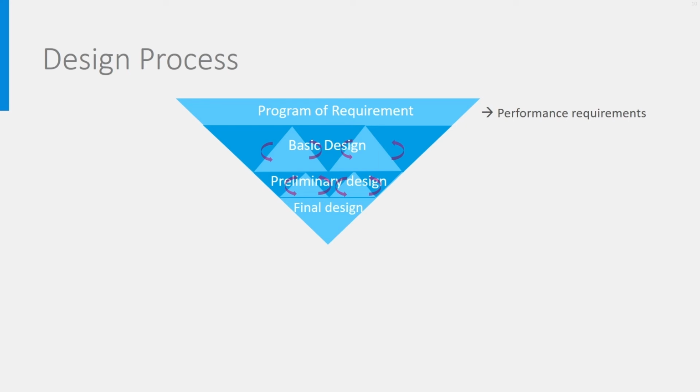After that, there may be a tendering or awarding phase, and the constructor will start with building the building and its systems. HVAC engineers may then play again a role in supervising the HVAC construction and taking care that all delivery procedures and needed checks are done. Think of checks about compliance of insulation, boiler temperatures, heat and cold delivery in rooms, quality of ventilation, etc. This is a phase of tuning of the equipment.